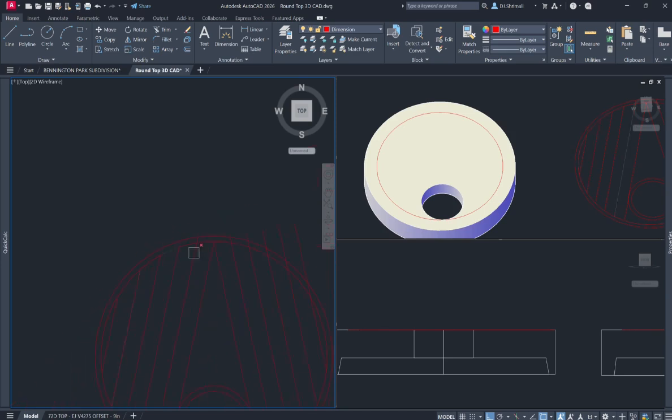Like a diagonal or tangential from the hole. So if the hole was on the center, these rebars will be perfectly straight, not tangential, just straight, number 6 on 6 in both directions, or whatever the engineer decides. If it's number 6 bars at 6 inches, number 6 bar at 4 inches, or number 6 bar at 10 inches, whatever it is.